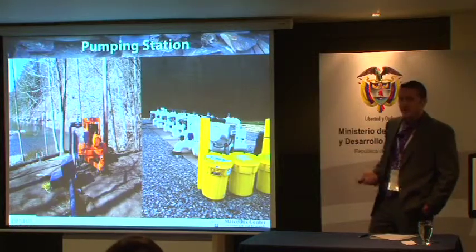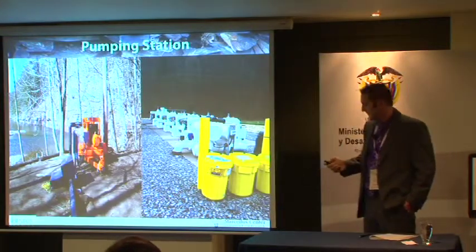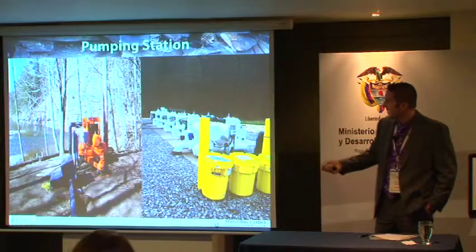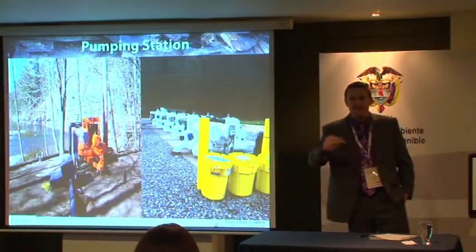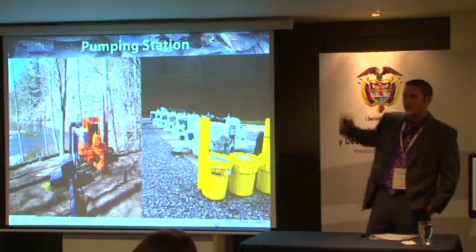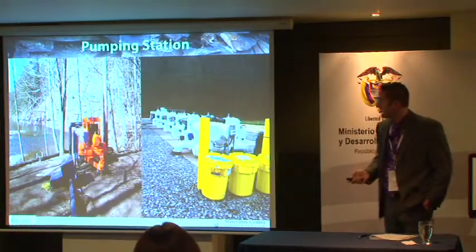And this is actually the pumping intake for that piping system I just showed here. So they have the pump. They run it through some filters just to get out the suspended sediments, and then run it up through the pipelines to deliver it to the well fields.